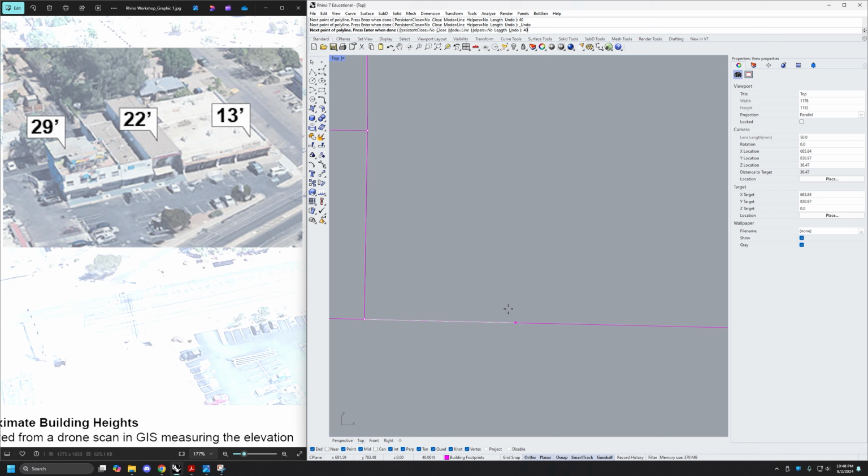I'm actually going to click this next point without it being on the node, but you can see how it's snapped to that area right on the line. If I click here, it's going to put that point 40 feet away. I think what was happening is I was referencing too many points, and that smart snap was having trouble finding out. So yeah, you'll get a little preview by seeing that pink node.